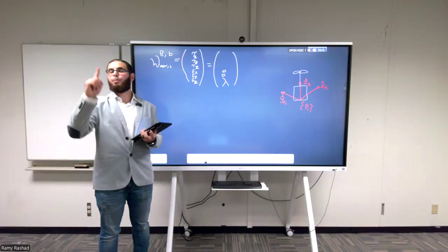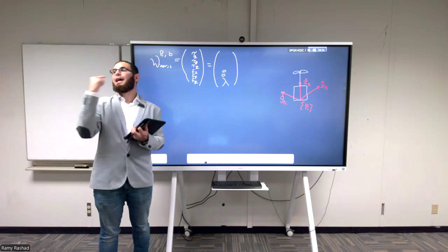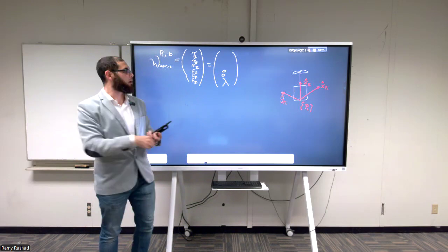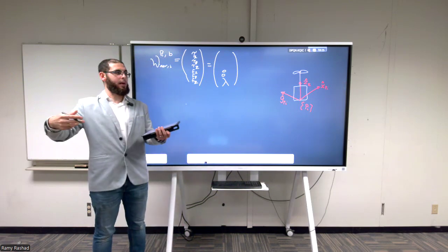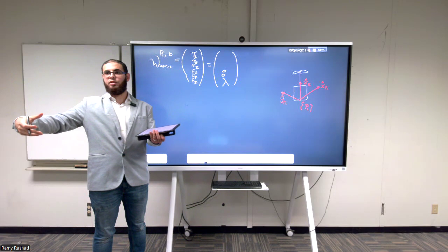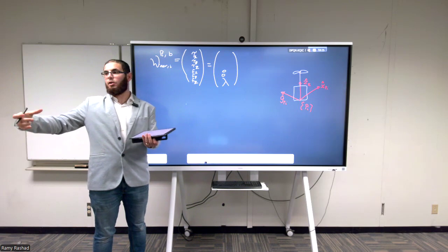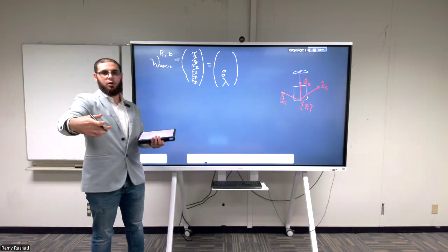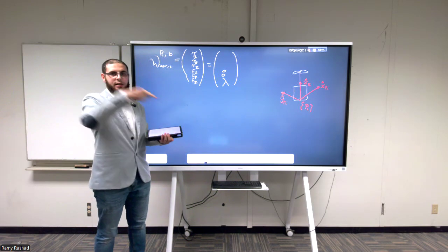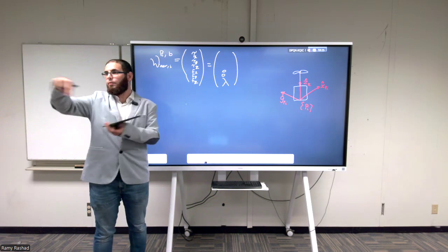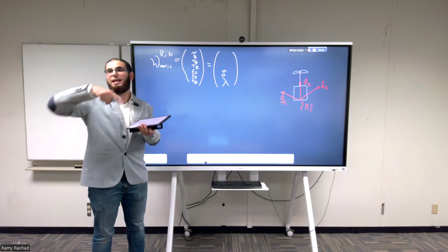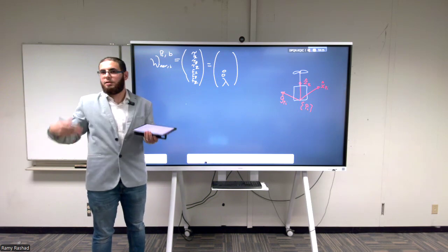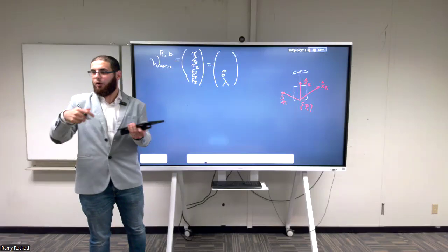So whenever you rotate a propeller, you always have a reaction torque because of the drag. This reaction torque can be positive or negative, by the way. That's why, for people who have worked with drones before, usually you have propellers where one is counterclockwise and one is clockwise, so that you can have these different directions of the reaction torques so that they can usually cancel out and you don't need to spend control effort trying to cancel them out.